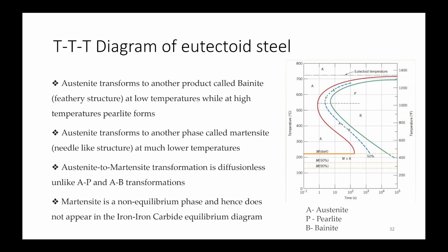Actually, we can justify it for the left part. There is a diagram from the previous lecture. For the eutectic alloy system, the melting point will be lower than A and B. It is characteristic of eutectic compositions that they have the lowest temperature.